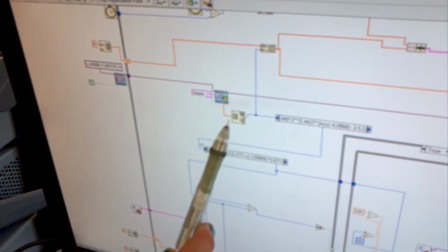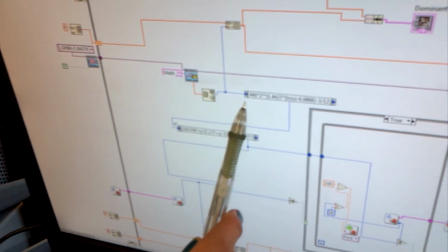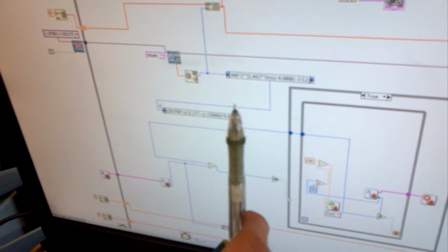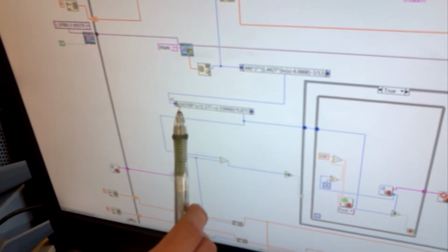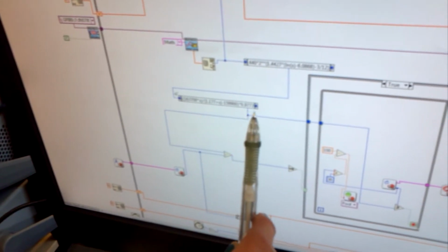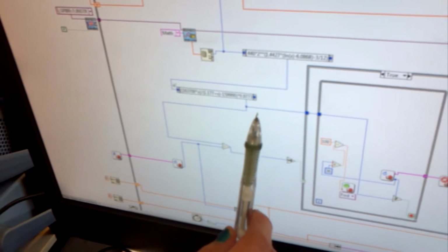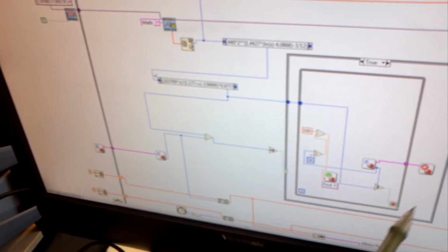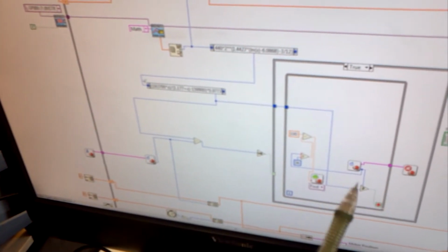the FFT from the oscilloscope, determines the dominant frequency, which is the frequency having the largest amplitude, and then we determine a harmony, which is a minor third below the dominant frequency. Here, that desired harmony frequency gets converted into an angle, which we had to do some calibration and MATLAB fitting in order to determine. And then from there, it's a lot of code to get the motor to move through that angle and recognize that it's actually there and stop.